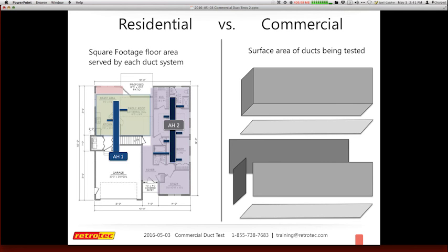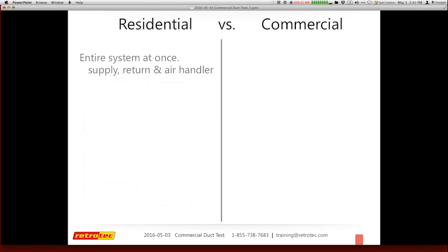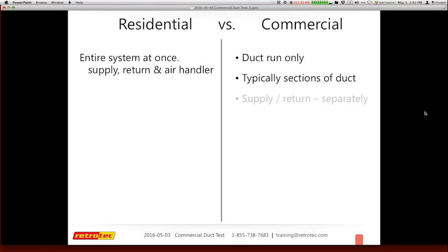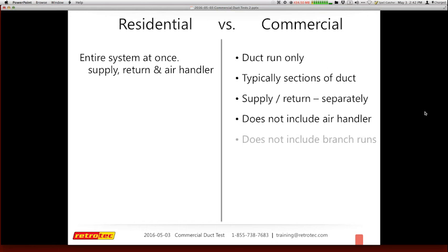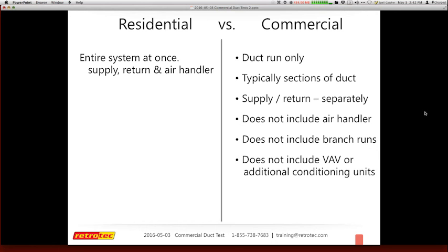So here's a couple of different things that you're going to be aware of when you're trying to find out what type of seal class. That's where we're going to start by reading here. So I'm going to do a seal class, and a seal class also usually determines my test pressure. If I have a seal class of C, B, or A, I try to color code those, because if I come down below this section, then it tells me what it is I have to actually seal. So the sealing of these types of systems is based upon what you call the seal class, for obvious reasons.